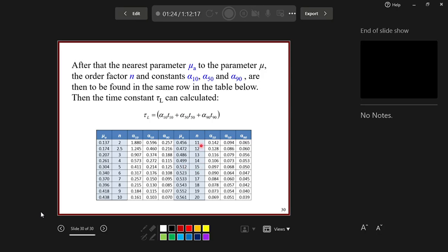The order can go up to 50 or 20, but just to let you know that in process control we don't prefer to go for orders greater than 3, because this simply means that the process is very complicated, and this will cause us a lot of problems when you come to the control system design. So we always try to approximate processes using first, second, or maximum third order.